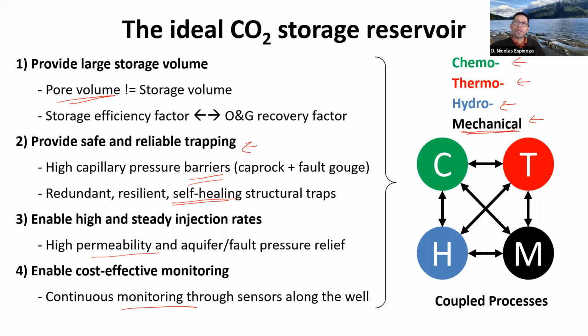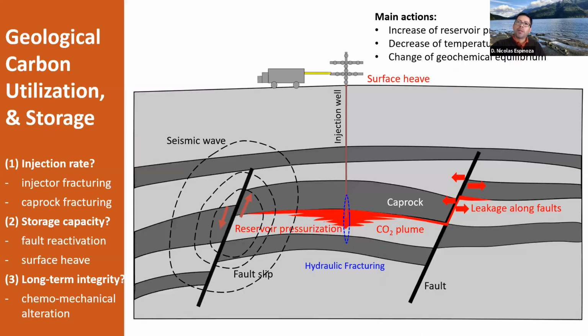All right, let's go into the specifics of this problem. These are the three main things that we're going to have to take care about when we consider geomechanics in carbon geological storage. First, we need to get to know what is going to be the injection rate. And we have to make sure that that's not going to fracture the injector or the cap rock, because that will defeat the purpose of keeping the CO2 in the subsurface.